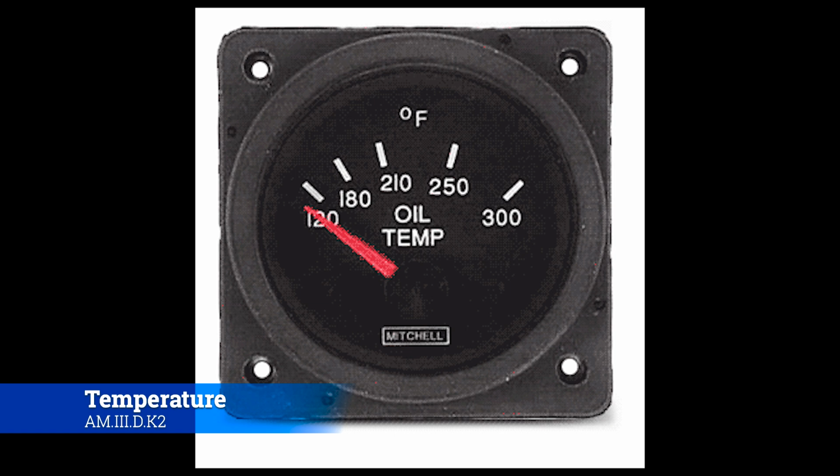The other scenario where you get really warm oil is that if the oil starts to break down over time, if it's been a long time between oil changes, what happens with oil is that as it gets heated up and cooled and heated up and cooled, it's effectively being refined even more than it would be inside of a refinery. And so you're getting that oil to start to break down and become thinner and thinner. And as it becomes thinner, it can't hold as much heat.